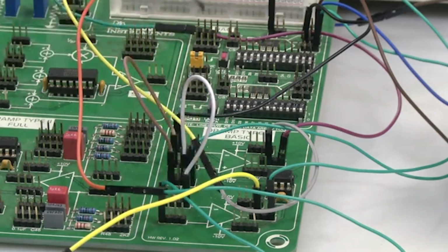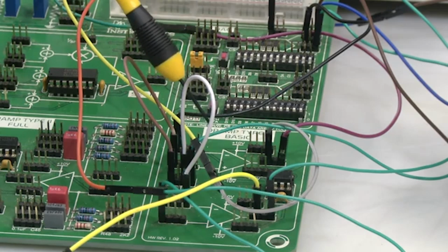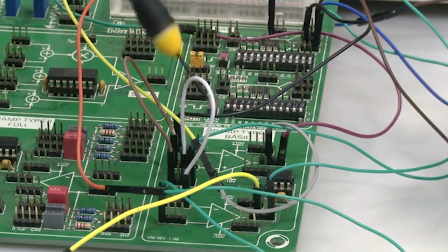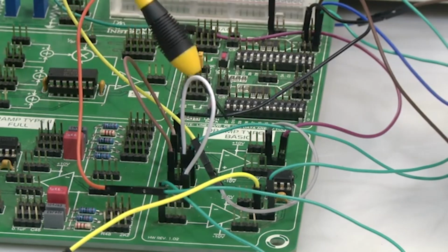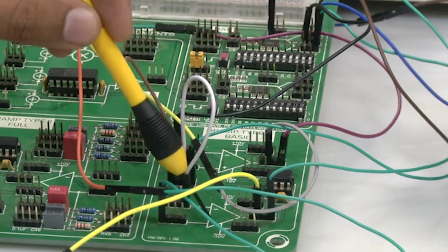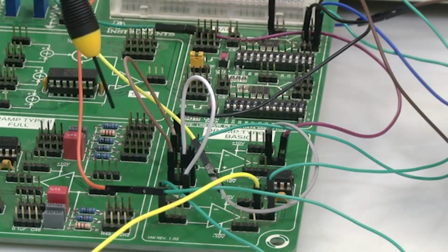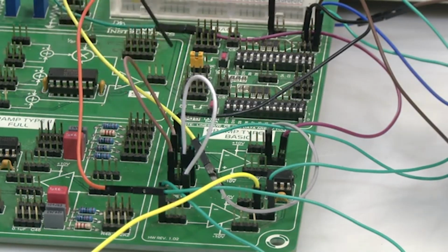One op-amp, as we have seen, is used to convert the current output of the DAC to voltage, and that gets fed back into the feedback network, correct, and then is used up by the other op-amp, whose output goes back as the Vref for the DAC, correct. So these connections have been made here. It looks like a lot of connections, because we are using the jumpers on the board and connecting them up, but the basic idea remains the same.